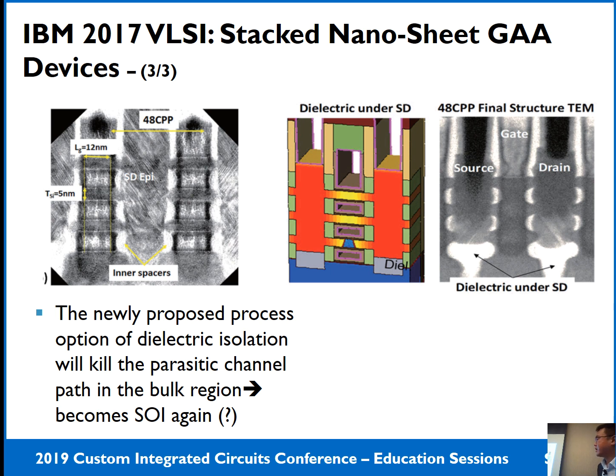So in order to kill this parasitic channel here, at IMEC we use what we call the ground plane implant. We just increase the dopant concentration here and make the VT higher. Then in normal circuit operation, you will not see this channel here.